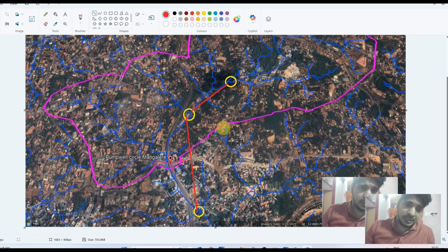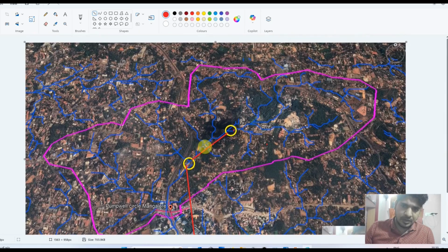And the first option, as I mentioned earlier, is re-widening of the existing drainage system, considering the 20 to 25 Qmax of the peak flow. That is where I used the thumb rule. It's not an exact figure, but it's based on my engineering experience. This area is 3.5 square kilometers, and it's not fully developed. It's a semi-urban kind of catchment. These are the two possible solutions I brought.